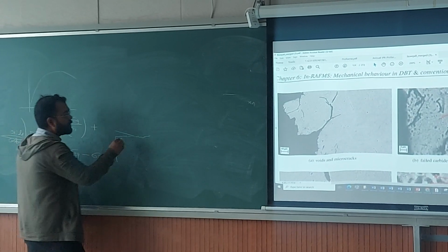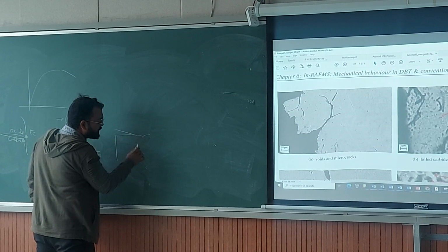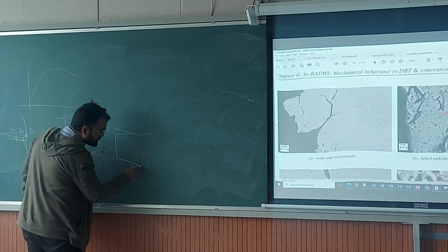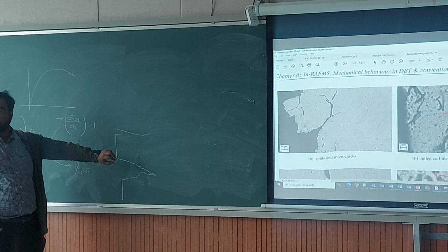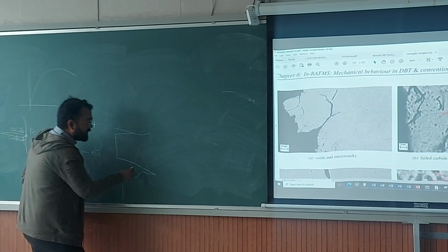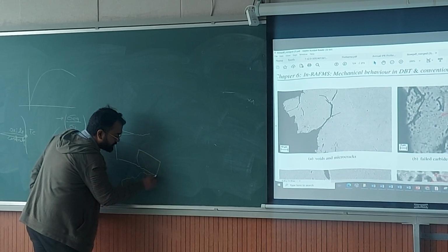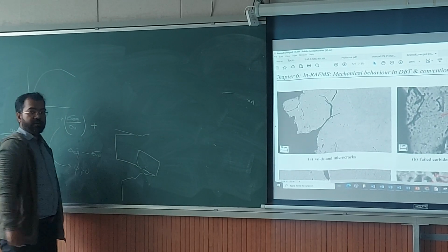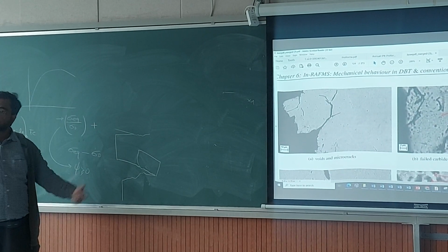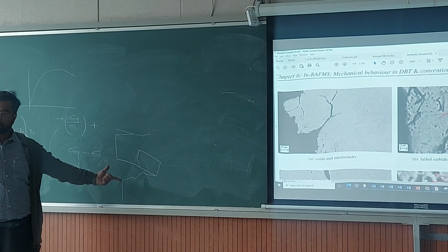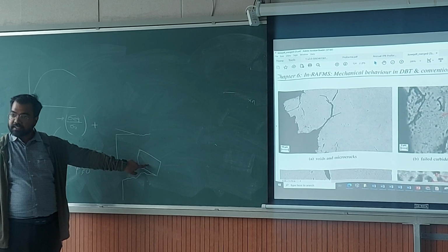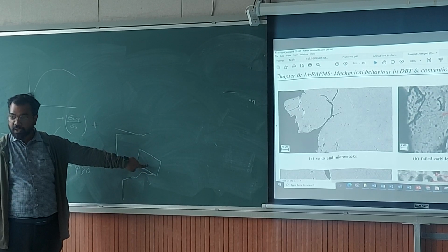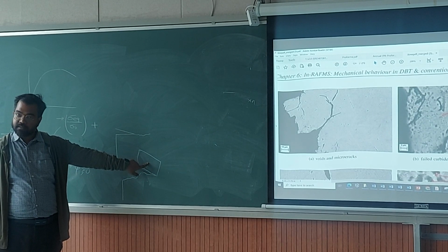Okay, and a small piece was, so this has propagated, so it has opened up. And this is an exaggerated view, it really doesn't look like this. And then you take a small piece here, polish it, etch it, then look at it. You can also see without polishing, and you will see the crack profile. But if you polish and etch it, then you will also see the grains and boundaries and carbides.